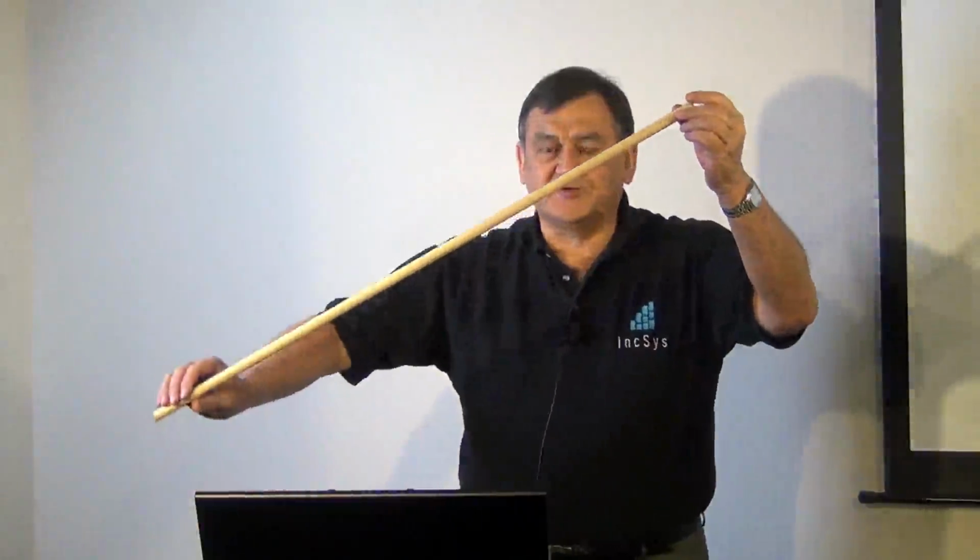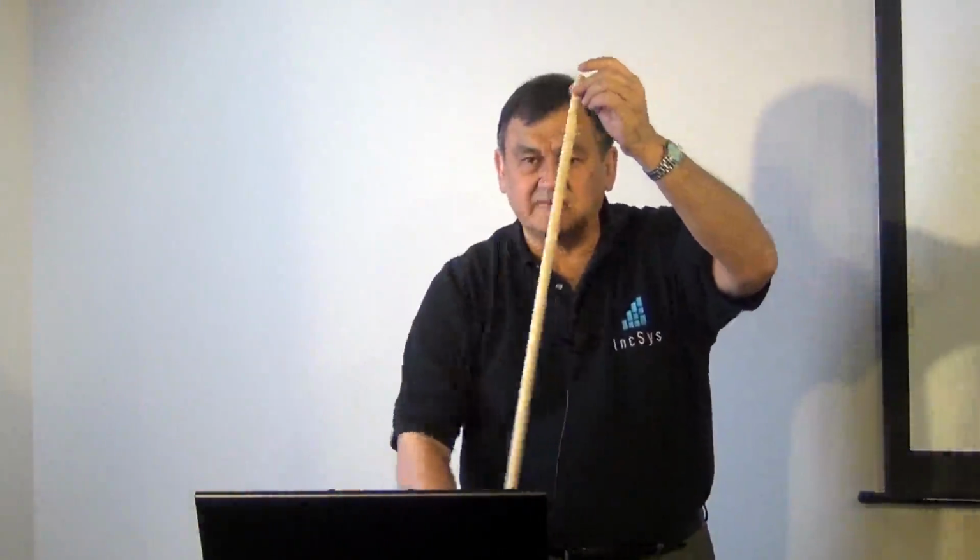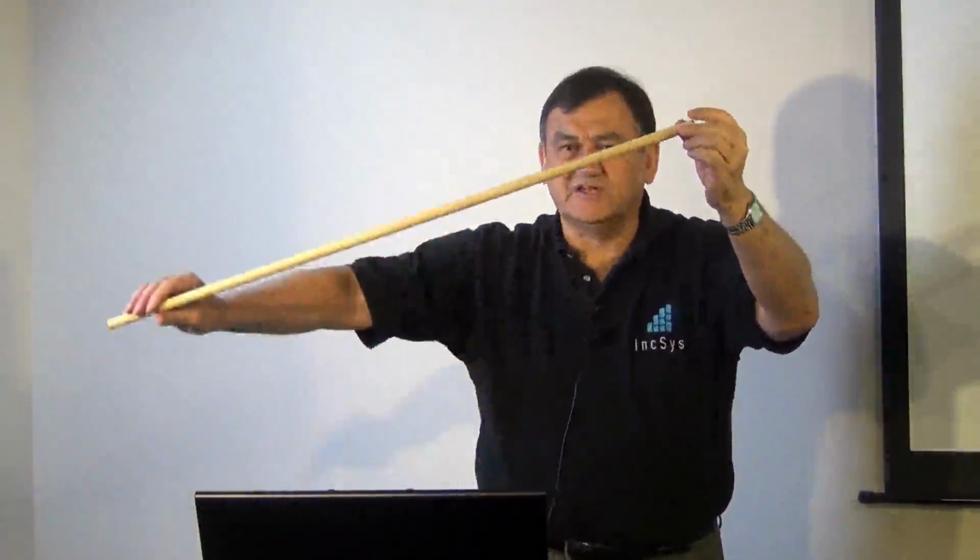So basically, whereas in the mechanical analogy we were talking about the difference between kinetic energy at the bottom, where it's going fast, and potential energy at the top, in the power system we're primarily dealing with an exchange between energy in magnetic fields and energy in electrical fields. The magnetic fields are the inductive devices, like the motors and the transformers. The electrical fields are like the capacitors.